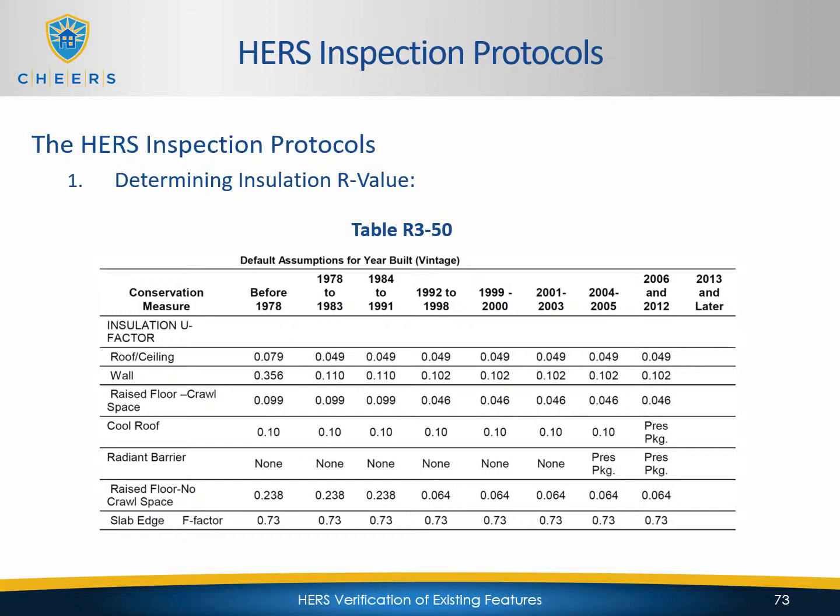Now, one thing you want to keep in mind is the fact that this particular table is giving you U-factors. So you have to convert it to R-value, just like we had talked about earlier in the Title 24 overview and the principles of building science.